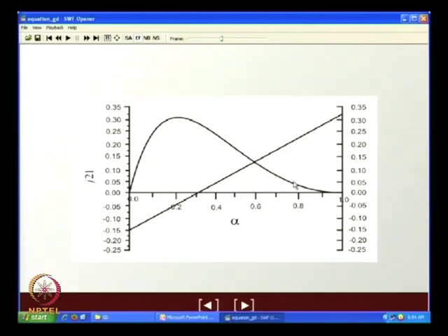as expected. Here we find that alpha occurs at a higher gas velocity, because for co-current downflow, if gas velocity is not quite high, we cannot obtain a stable flow pattern. Okay. So, this was the point of intersection for co-current downflow. Now, let us take up countercurrent flow.